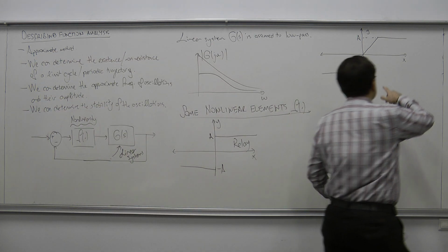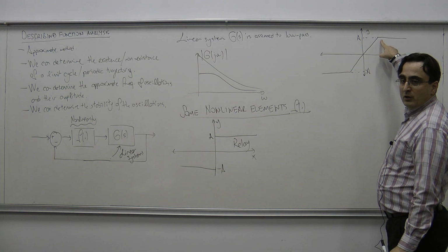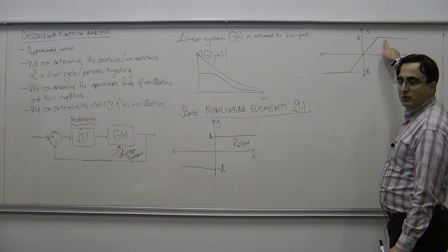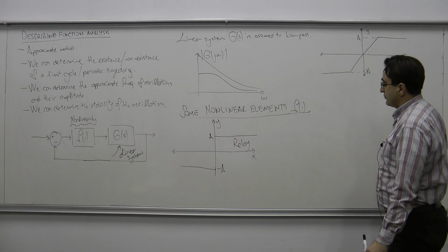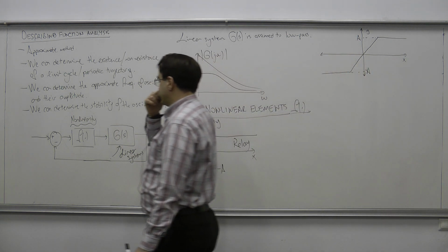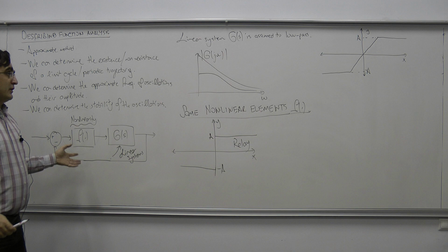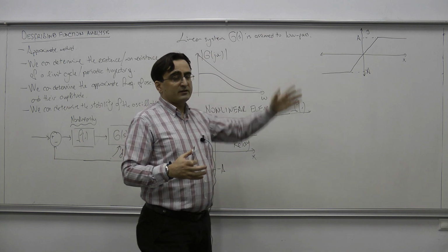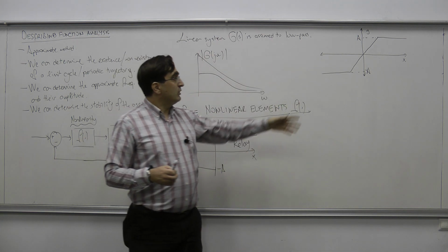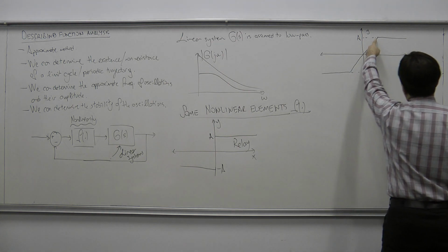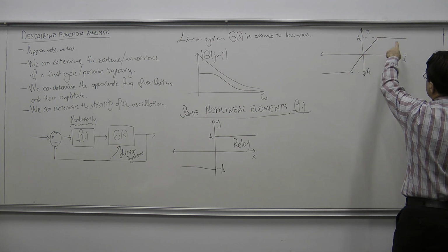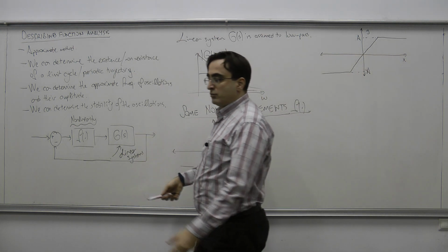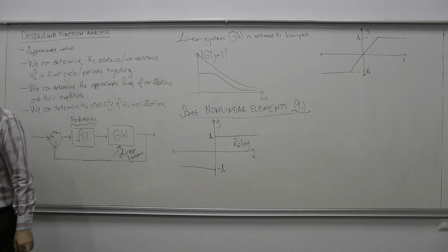So if you ask for a larger torque than the maximum torque that can be supplied by the electric motor, it's going to supply the maximum torque to you. Okay? In that case, this type of saturation element would make sense. So your physical system, your actuator, has some limits, and it cannot supply torque with a magnitude larger than a threshold. Then you can put this in your mathematical model to model those saturation effects in a better way.